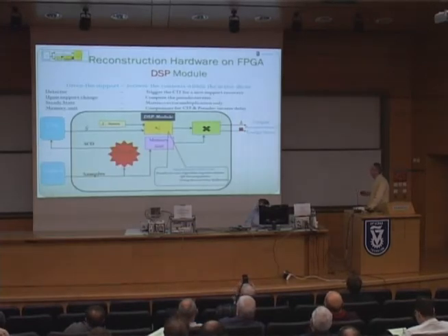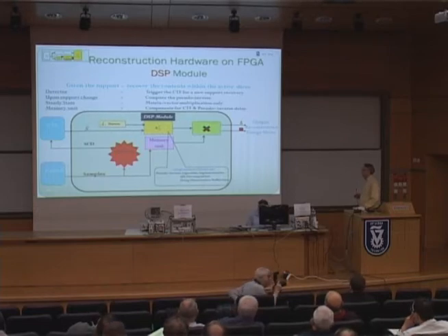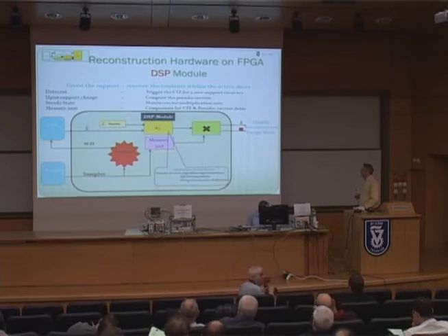Finally, we have here the DSP, which is performing the rest of the task. So we get the samples from the expander, and it gets the supports from the CTF. We first have to do the inversion of our matrix. This is, if it is one line in MATLAB, it occupies some portion of the FPGA, and we have adapted this one also to hardware by using Householder reflection in the QR decomposition. Here is the reconstruction of the slices.